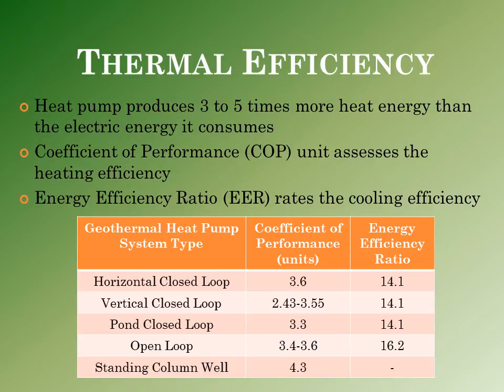Here's a table comparing the EER and COP of closed loop, open loop, and standing column well systems. The COP in standing column well is the highest, meaning that it is the most efficient when it comes to heating the building. The EER in open loop is the highest, meaning that using an open loop system to cool a building is the most efficient.